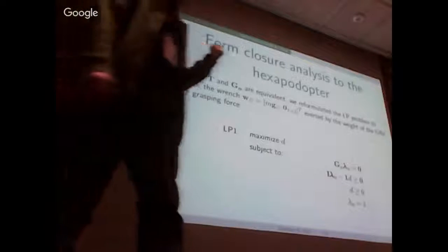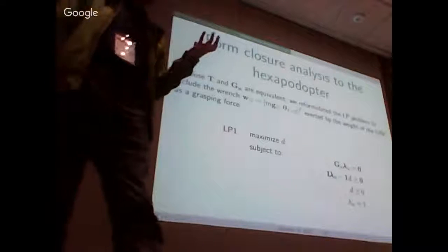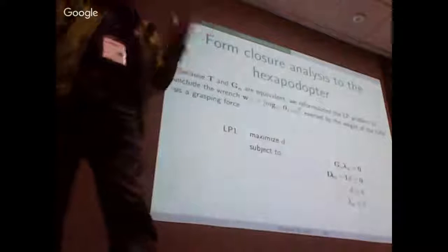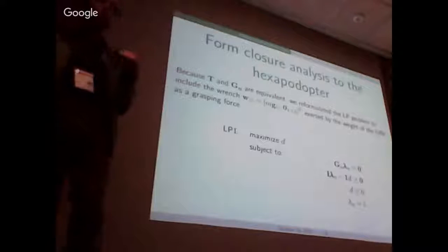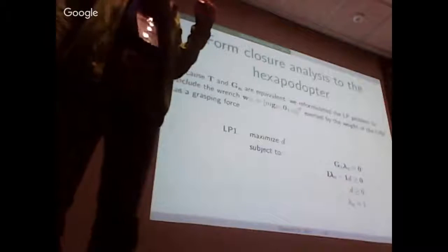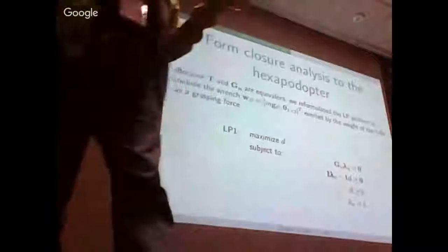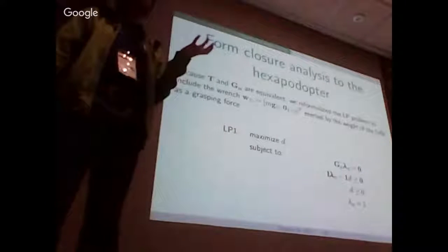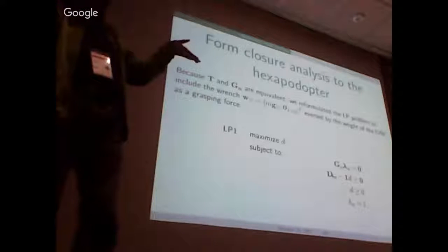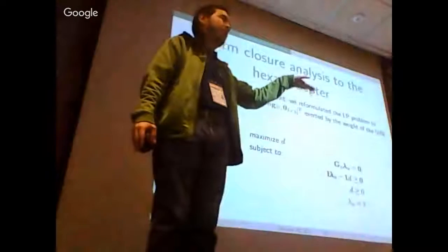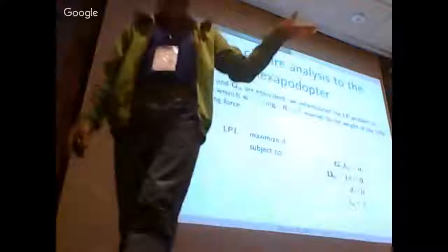So if it is a form closure arrangement, we can exert a force or torque around the center of mass of the vehicle in any direction. Under that assumption, the vehicle can move in each direction without tilting, as a normal vehicle does. Right? A normal vehicle has to tilt first to gain horizontal acceleration, it tilts backwards to decelerate and brake, and then forward again.